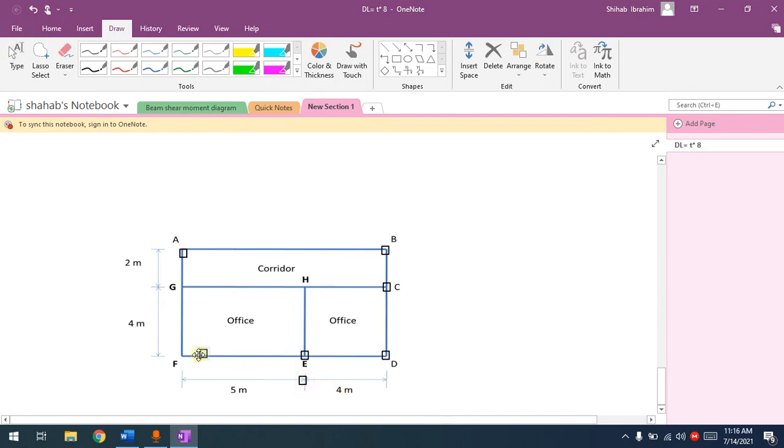If there is a connection between beams and there is no column, remember this please, you have to provide a point load. Let's say I have it like this. There's only one point where there is no column, which is H, the interconnection of these beams, and we have to provide a point load.